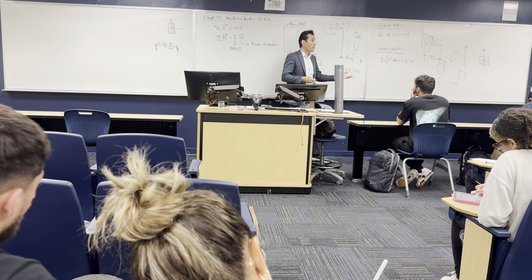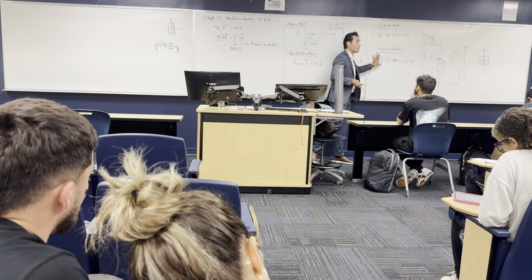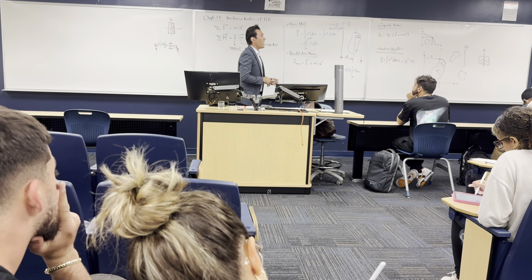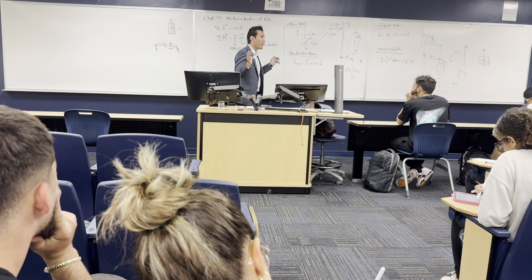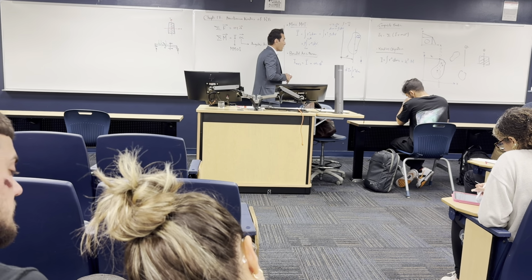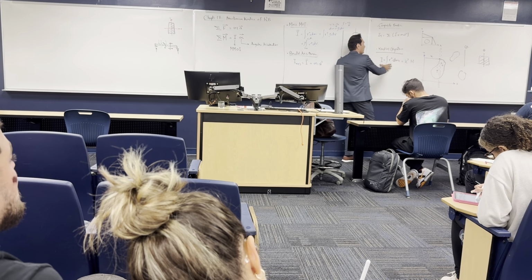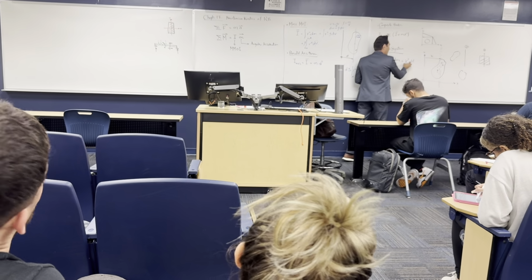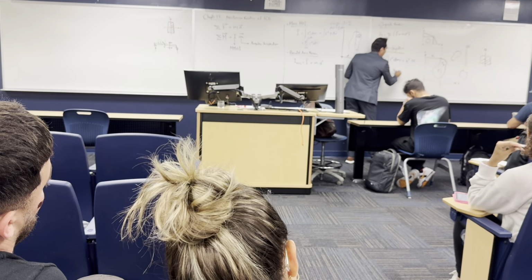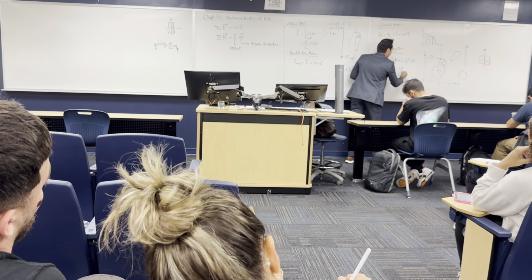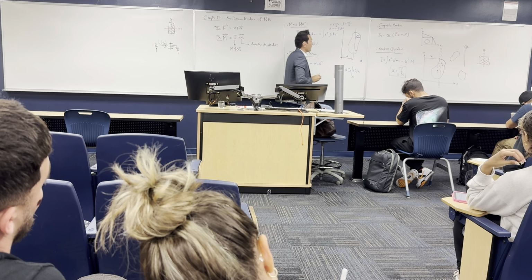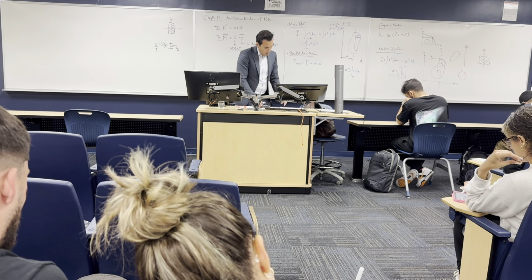The larger the radius of gyration, the larger the mass moment of inertia. It's kind of like an index. Think of it as an index to see what the mass moment of inertia looks like. So basically, you have to get the inertia, and then you need the mass if you want to get k. So k is going to be equal to the root of I over m. That's what the radius of gyration is.